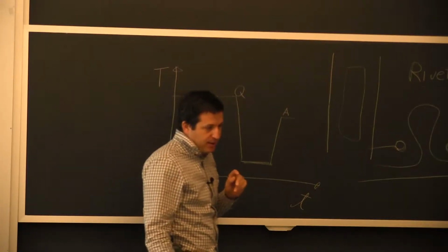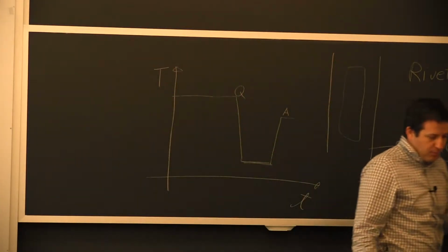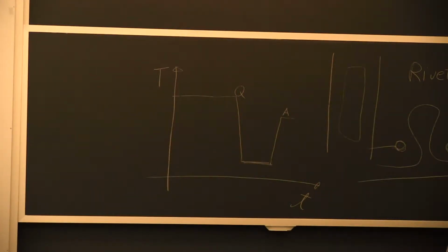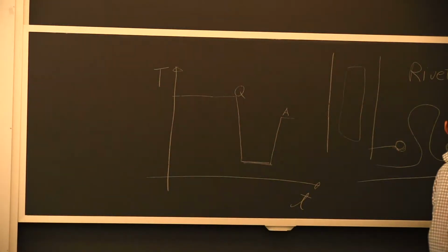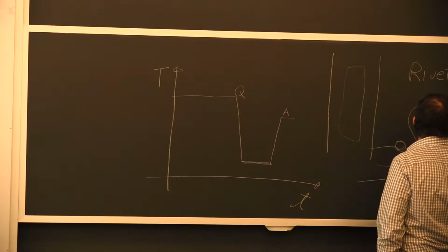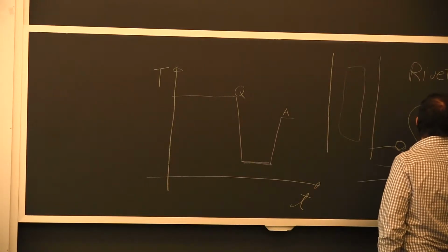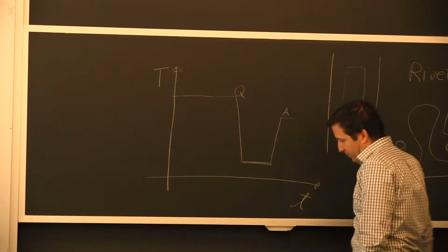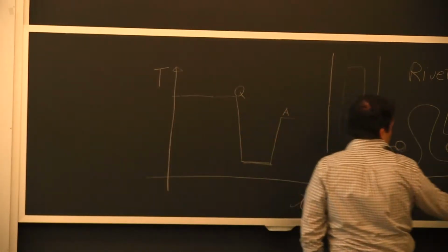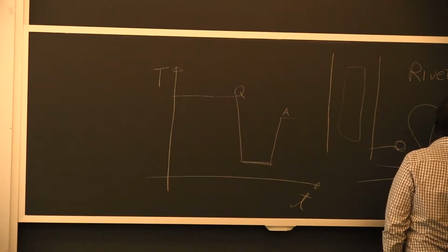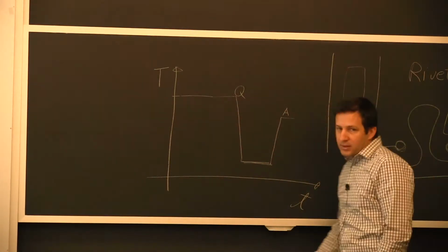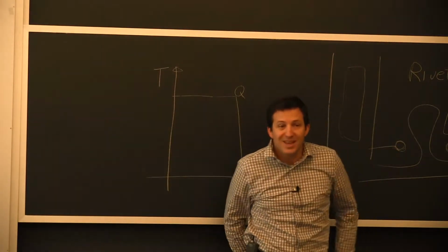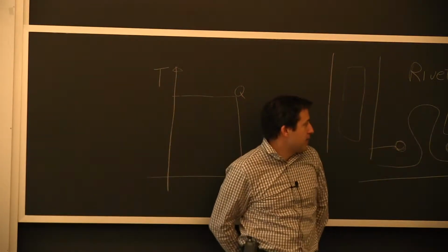And that's essentially what will change this whole treatment. So Professor Eager mentioned 6061 as being a very typical fabrication alloy. It's being welded a lot of the time in T6, which is the high strength temper. It's close to the peak hardness.